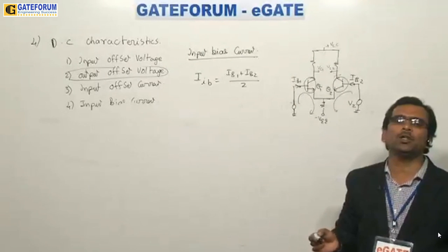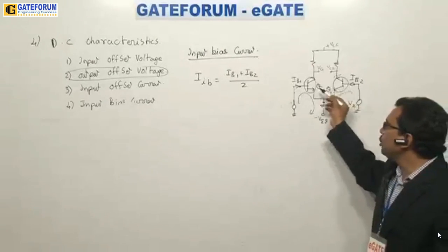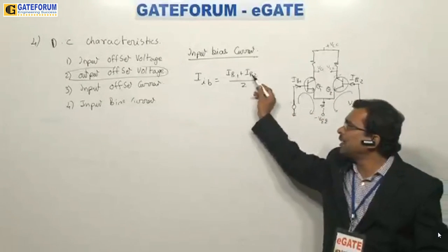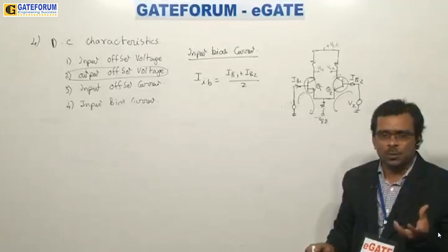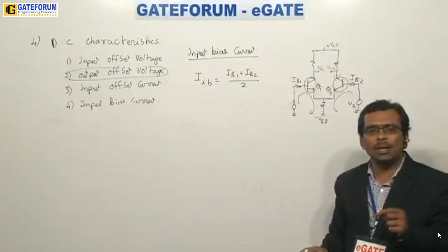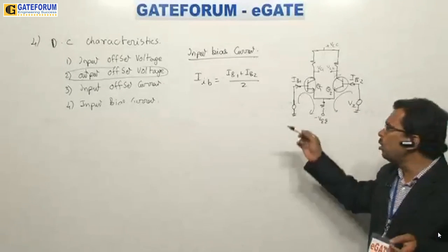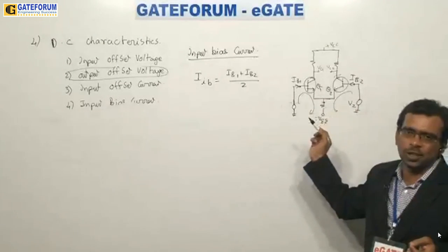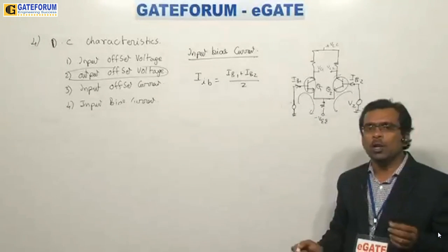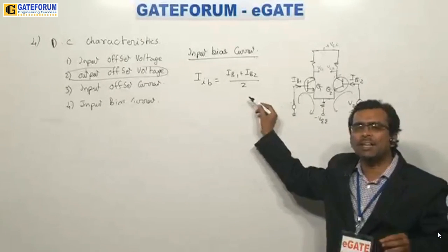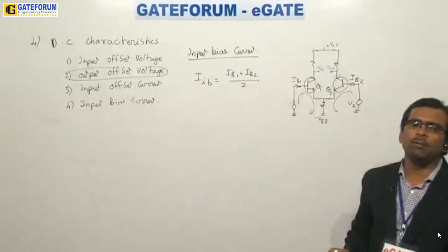So you make your mathematical calculation before manufacturing the device, but after manufacturing, due to the mismatch in the transistors, the biasing currents will differ. Then you will not have the exact value as expected from what you calculated mathematically; it will not meet the practical value. So power dissipation will be more due to the DC values at the resistors. Instead of taking them equal, we take the sum of these two and calculate the average. Then only you will get the actual power consumption by the base current for the biasing.